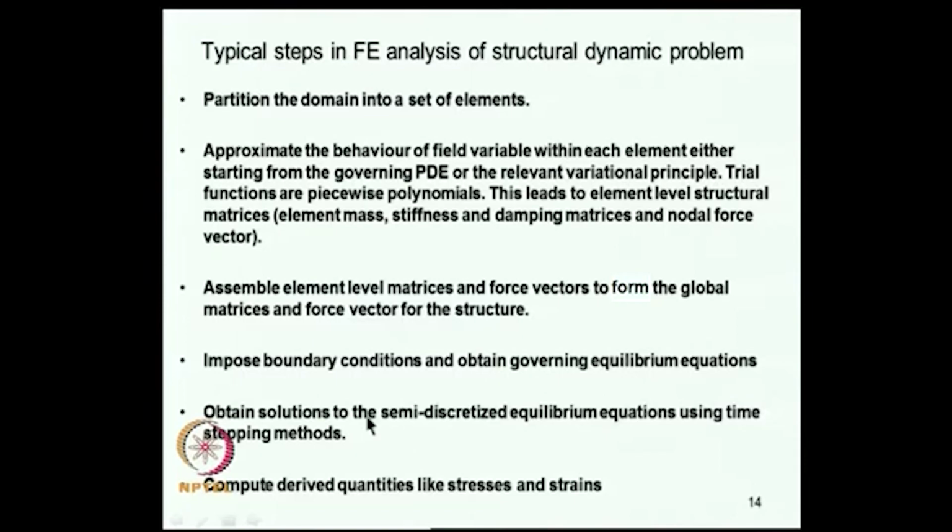Now, for this set of ordinary differential equations, we address the question of discretizing the time. So, we typically use time stepping methods, explicit or implicit depending on the details of the problem, and this completes the determination of the field variables at the nodes. Then we compute derived quantities like stresses and strains.